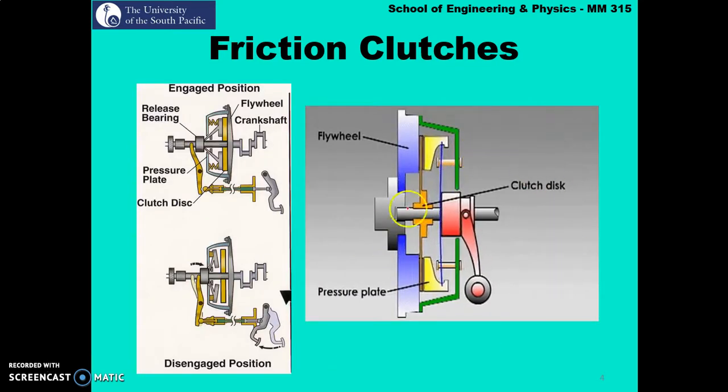In this animation, you can see how a clutch disengages and engages. Here we have a lever fork. As soon as you press onto this lever fork through the clutch pedal, the lever fork moves in and it presses onto the diaphragm spring. The diaphragm spring at this end causes the pressure plate to move outwards. As this happens, you'll see that the clutch disengages from the flywheel.